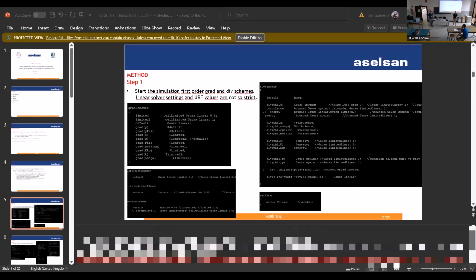If you use the tetrahedral mesh, maybe we can assume it is highly skewed, right? 70 degrees, 71, 72 is skewed actually. For the tetrahedral meshes, for the volume mesh part, I use Fluent meshing, but for the surface mesh, I get it from Pointwise. Okay. I export that, because I trust it more for the volume mesh.